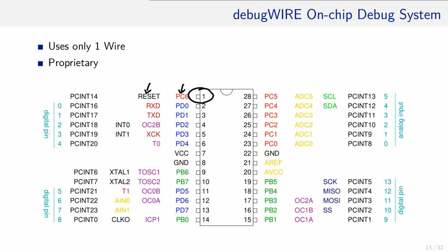First, the advantages. Using a pin that is usually not used by any periphery seems to be a very good idea. No replanning or redesigning of the periphery connections nor alterations in the software are required. Now the bad news. It is using the reset line. How do we reset the ATmega now, which we need to do every time we would like to reprogram the flash once we found a bug? And finding a bug is very likely as the program is currently being debugged.